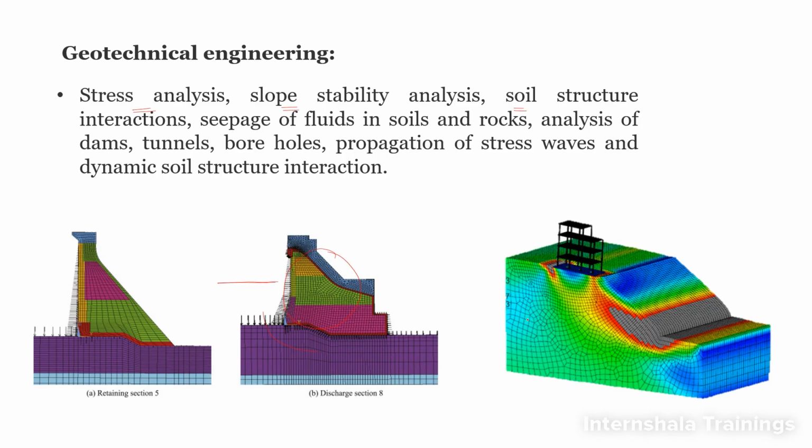And even see, if this is the case where there is a slope and I have a building like this, now I can simulate using FEM and tell whether this particular slope is going to bear this weight or not, or otherwise this particular slope is going to get destroyed and destroy the building or not. These are a few examples where FEM is being used in the field of geotechnical engineering, or let us say civil engineering or architecture. And especially hydrostatic load application and stress analysis in dams is one of the most widely used applications of FEM in geotechnical engineering.